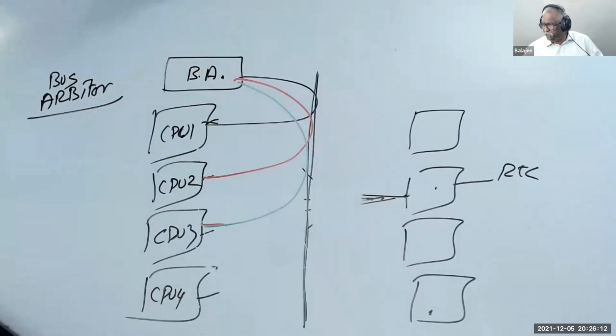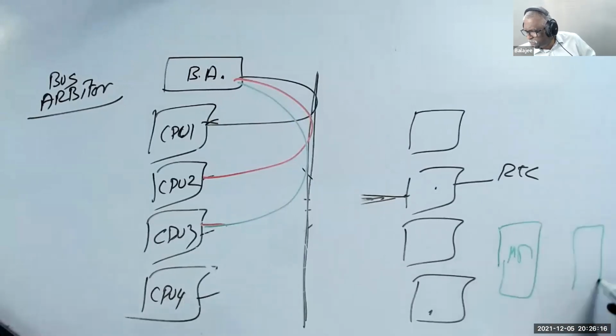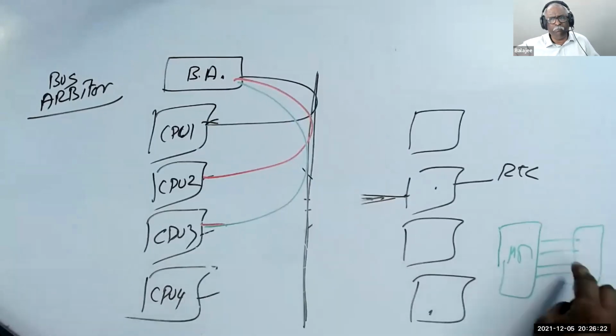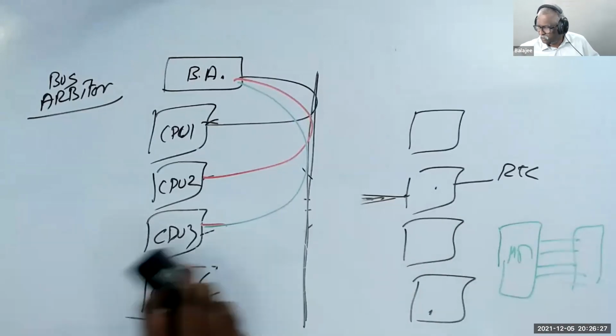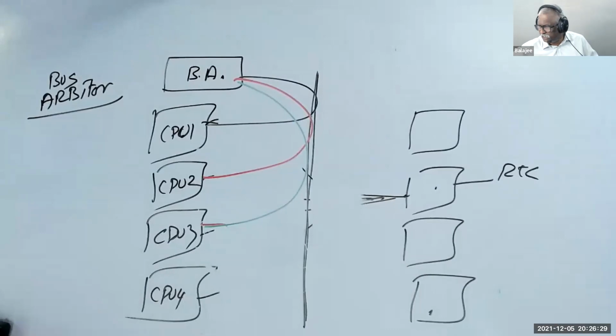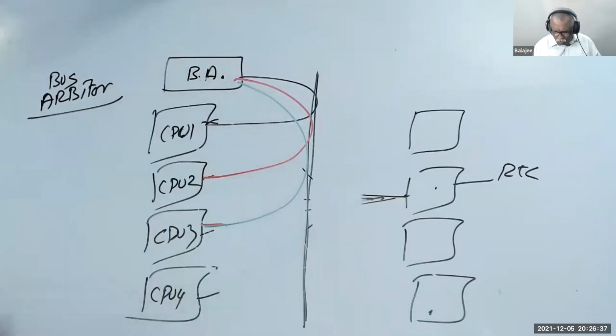What is the difference between what we previously discussed, a microprocessor and the CPU bus? That bus is tightly coupled. You have one microprocessor and all the others are slaves. We call this a master and this a slave, and the only exception is DMA. But you cannot connect general peripherals like that. So they have a bus arbiter. Now this guy will be talking to them like this.